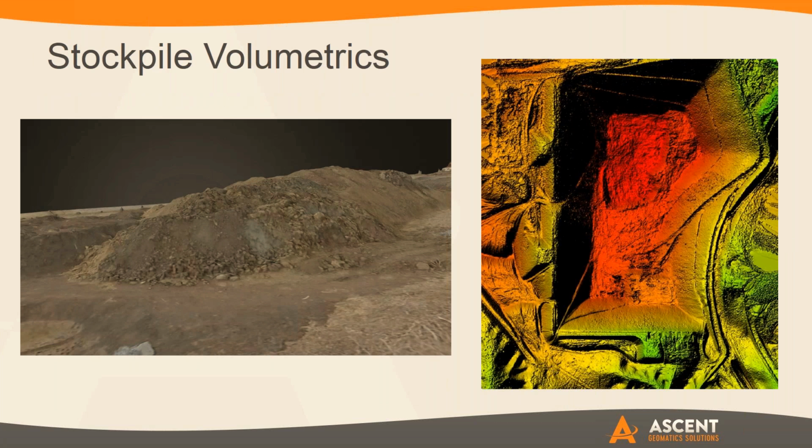Okay, great. So stockpile volumetrics, this is the one we talked about earlier, which is kind of a no-brainer. It's a much safer way, and you're able to collect more accurate data in much less time than doing this conventionally. Yeah, and we've done it with LiDAR and we've done it with photogrammetry, and truthfully, with photogrammetry the amount of detail is great, because you're getting it from above, you're preventing shadows from developing. So your accuracy, compared to a guy crawling around on the ground or even scanning it from the ground, is great from the air.